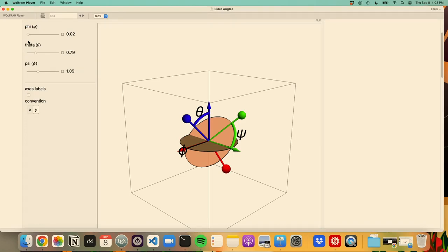Yes, good. Okay, so that was going to be the next thing I emphasize. The fact that there are multiple conventions. I actually illustrated two different conventions here. The first one, we were doing these rotations in a specific order. First about EX, then about EY, then about EZ. So that has a name. Let me just turn on the lights again. So what I described on the board over here is called the space 1, 2, 3 Euler angle convention.